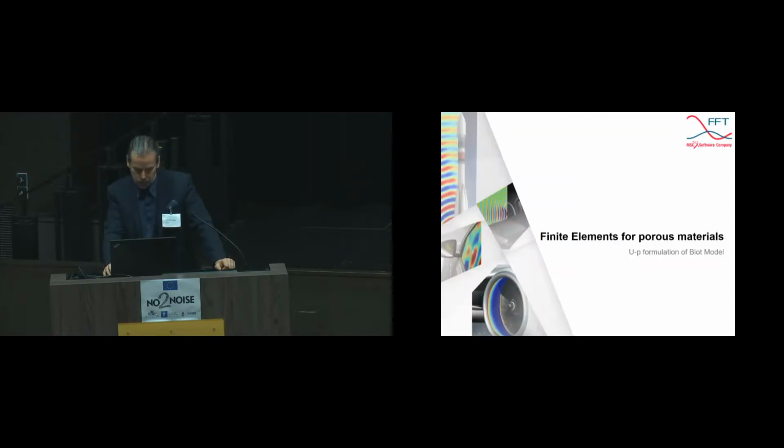Okay, so now maybe more details about the core of the presentation, finite elements for porous materials. I spent a lot of time on acoustic materials, not so much on structural elements, but it's normal because for all kinds of numerical models, we almost never use porous materials alone. They are always embedded, in contact with some vibrating structure and radiating, or coupled to an acoustic cavity. So it's very important to be able to couple those porous materials to numerical models for structures and for acoustic radiation or fluid cavities.